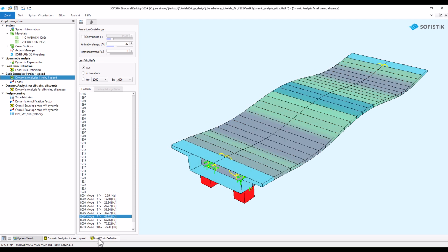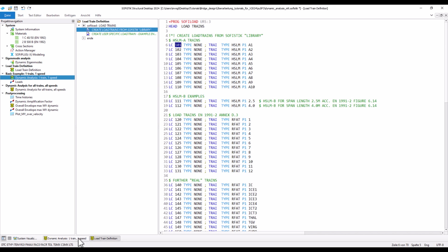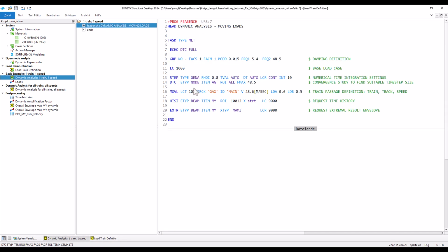With the resulting time step size, a dynamic analysis is then carried out, and for a specified result type, here nodal acceleration in gravity direction, the result time curve is computed. To check if this time step size already provides a good resolution of the problem, the result time curve is next recomputed using a smaller step size.